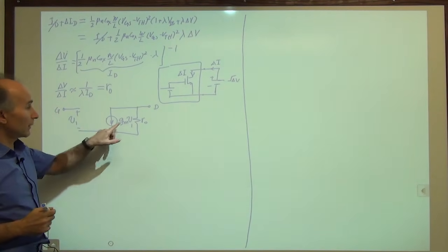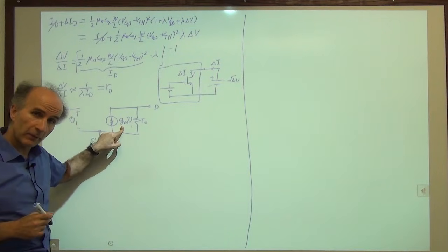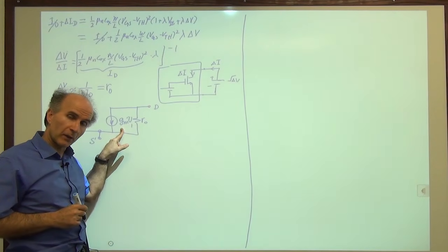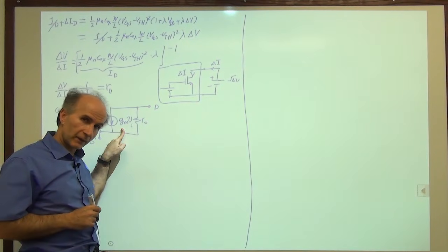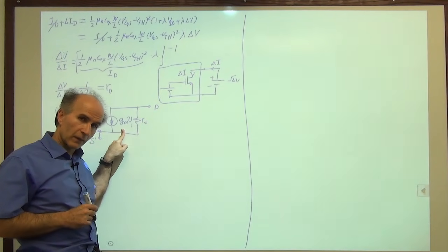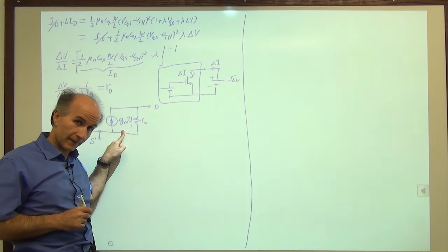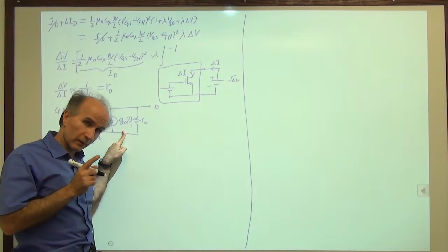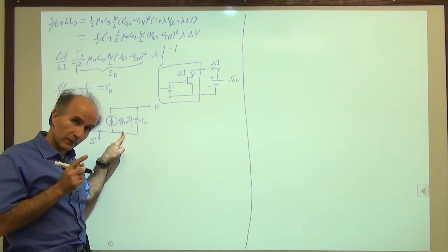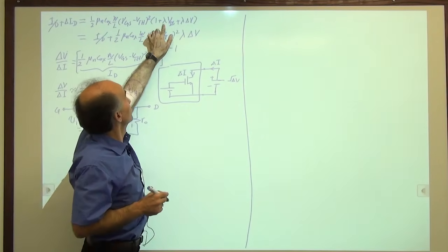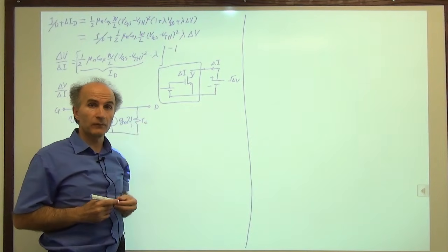Now, remember we had three equations for gm before? They were obtained by taking the derivative of the large signal model with respect to VGS. But in that large signal model that we used to derive gm, we did not include lambda VDS, if you remember.